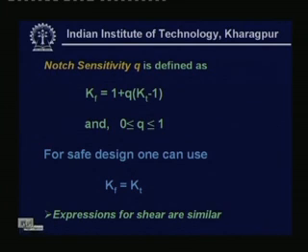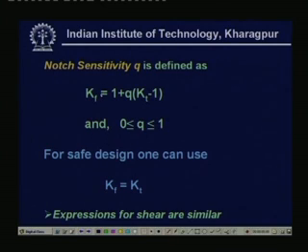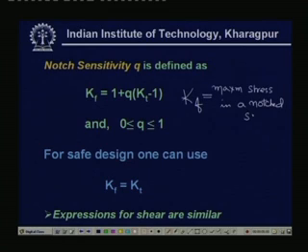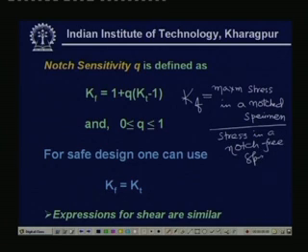So, if you want an independent definition of this Kf, then what we can write down, Kf is something as in ratio, the maximum stress in a notched specimen divided by stress in a notch free specimen.